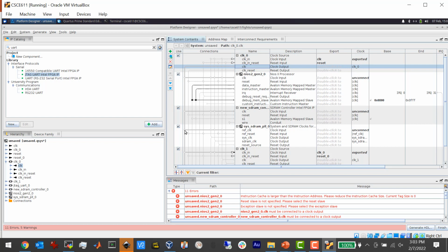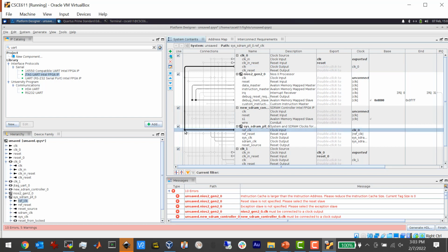You might be saying, there's got to be a better way to do that than finding bubbles in that thing. This is ridiculous. Nah, maybe with Tcl commands, but I don't see a Tcl console here, so unclear. I don't know how else to do this, but it is kind of silly. But yeah, so we're going to make this connection here. All right, now once you make the connection, look, it highlights that wire, so now you can see it's clearly connected there, right? All right, so now we've got the reference clock.